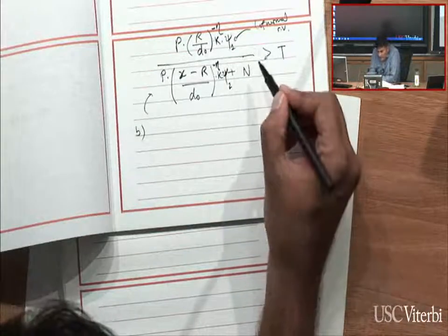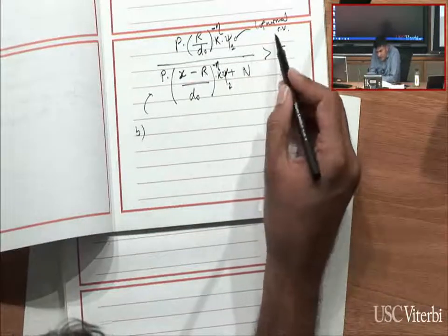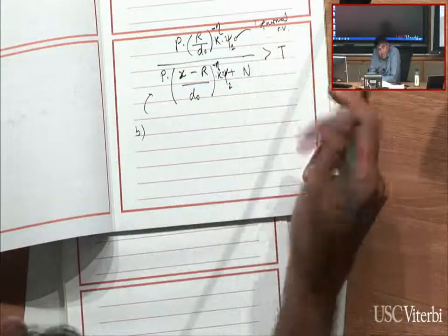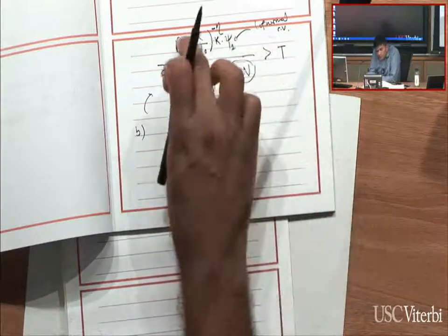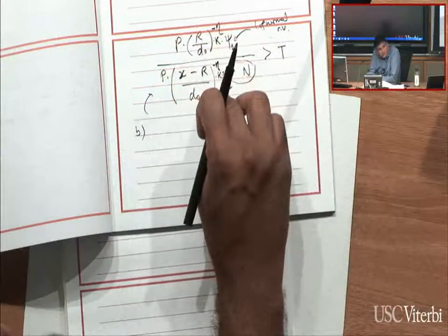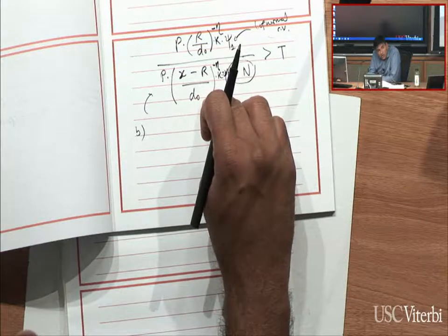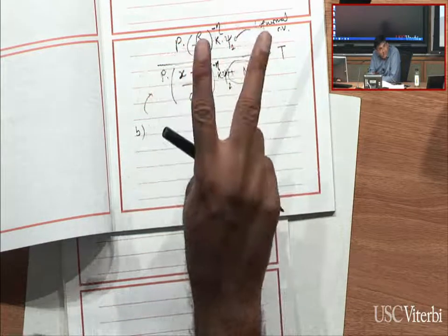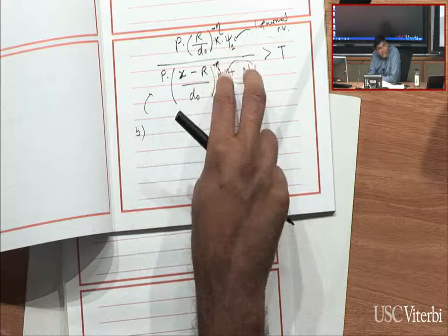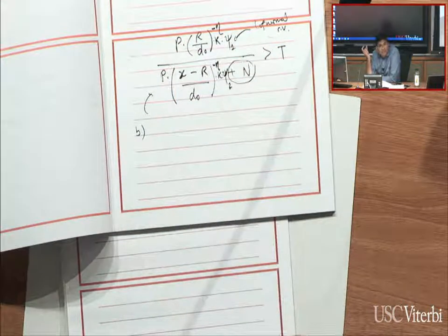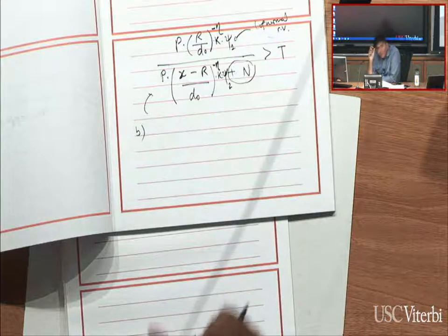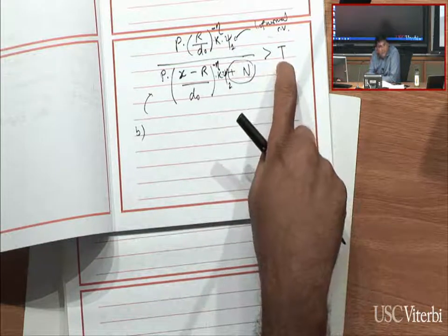And the insight was the following: if you look at a log normal random variable in the log scale, it is a Gaussian. Particularly if you can ignore the noise term, this ratio of signal to interference in the log scale is basically a difference, a dB difference between the dBm from the signal power and the dBm from the interference power. What is that difference? And we're saying we want that difference to be more than some number.